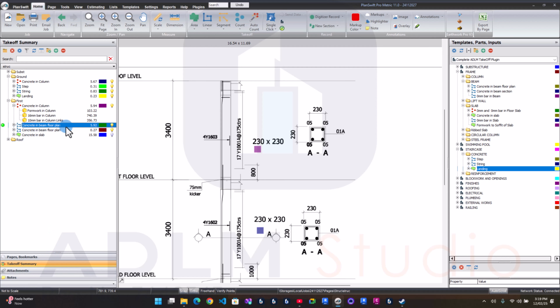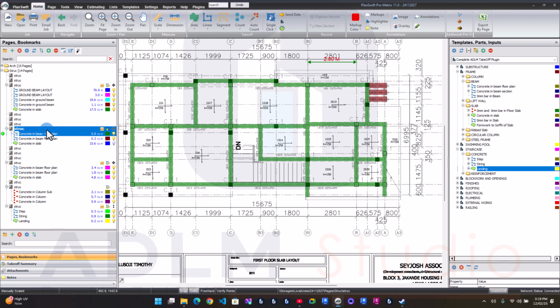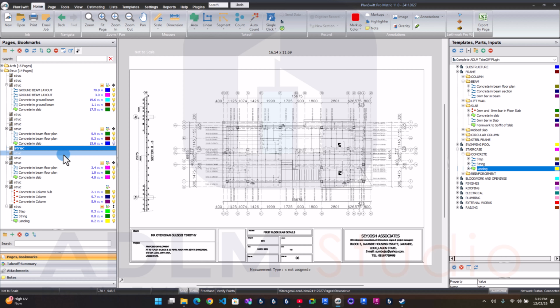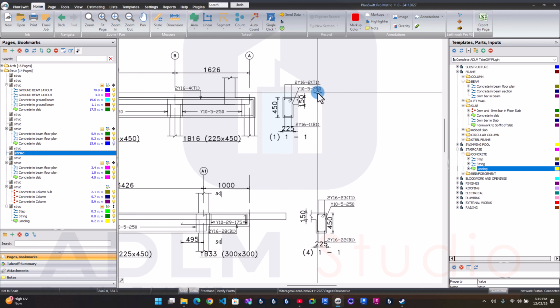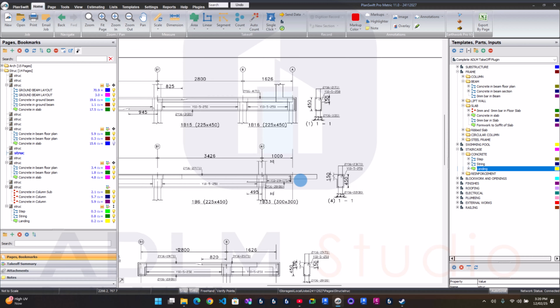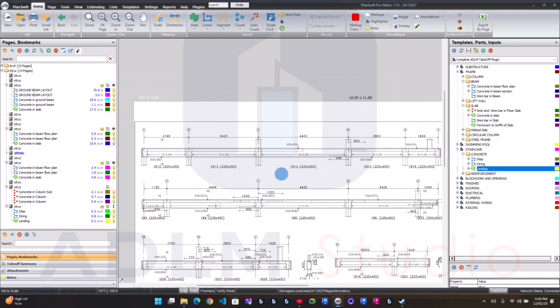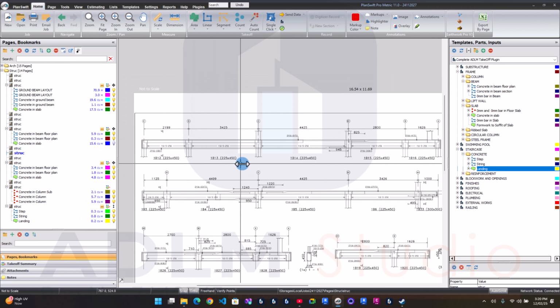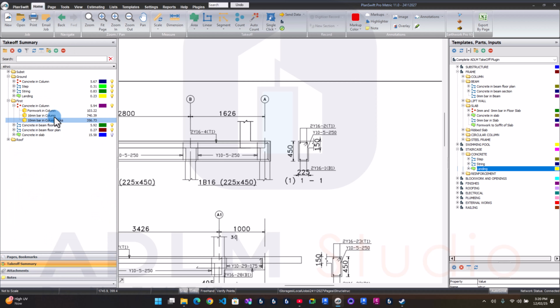So let me just go right click here, go to page this. So I'm on this page now. So inside this page I can just click. Let's see what we have for our beam details. So we have 216 up, 216 down, 10 links. You get 216. To check the drawing, it's literally 216, 216. So this length you can either use this method I'm showing now, or the second method, whichever works for your project. If it's consistent, if the perpendicular is consistent, you use that. If it's not, you use the other one. So let's use the first. Let me show you the first method.